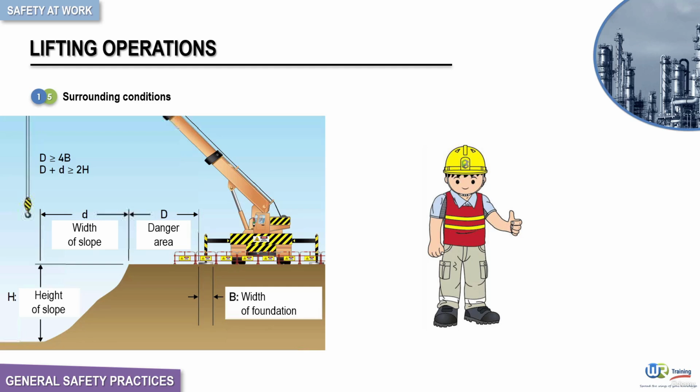The picture shown on screen provides guidelines regarding the various distances. For example, for safe and stable lifting, the crane should be located at a distance away from the slope greater than 4 times the width of the foundation.